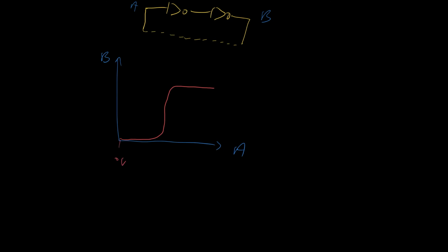So here we've got 0 volts, depending on the supply rail, maybe I make this 5 volts, and I make that 2.5 volts. And this is part of the fact that logic gates clean up noise that we've discussed earlier. So even if the input voltage is quite far away from a logic 0, when we get to the output, we're forced back to being very close to 0. Similarly, if the input is far from a logic 1, when we get to the output, we find we're very close to a logic 1, because logic gates tidy up noise.